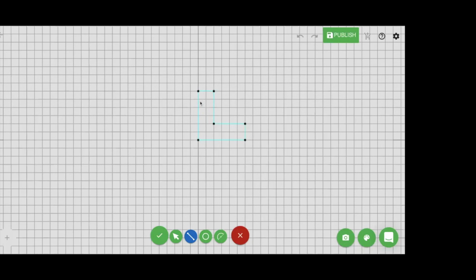And that's important because in a lot of 3D modeling platforms, CAD programs, if this wasn't closed and I then try to pull it out, extrude it into a 3D model, which I'll show you in a minute, it won't work because it doesn't know how to handle such thin walls, because according to math and computers, which is what this thing is doing, it thinks that this is an infinitely thin wall, and so it just gets confused and it doesn't know what to do with it. But when it's closed, it's water or airtight closed, now it knows this whole thing's a solid part, and now it's going to treat it as a solid model, and I'll show you that in a minute.